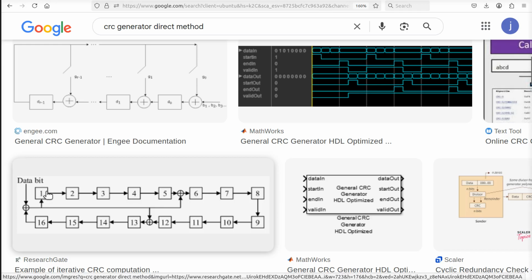Each time there's a clock, this is just a shift register that shifts everything around like this. And that's how the CRCs work when you build them to accept data 1 bit at a time in a serial fashion. You can do CRCs in other ways, but if you're going to do it in a serial fashion, you build a shift register and do this.